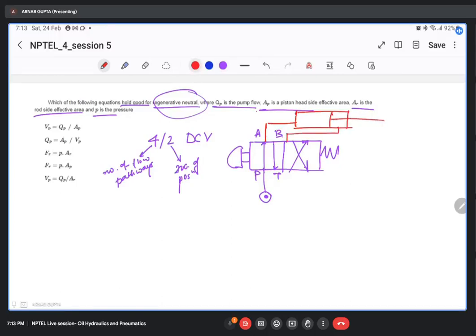Now, see, till the pump is on, as we push the switch, it will extend. If we release the switch, it will retract. Right. So if I keep the pump on, it will continuously extend, in either configuration, whether in this particular configuration of the ports or in this particular configuration of ports.